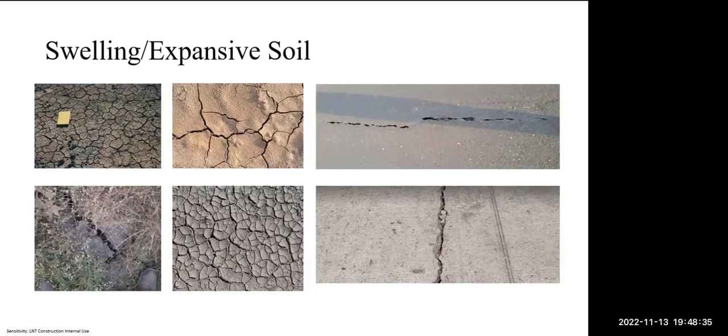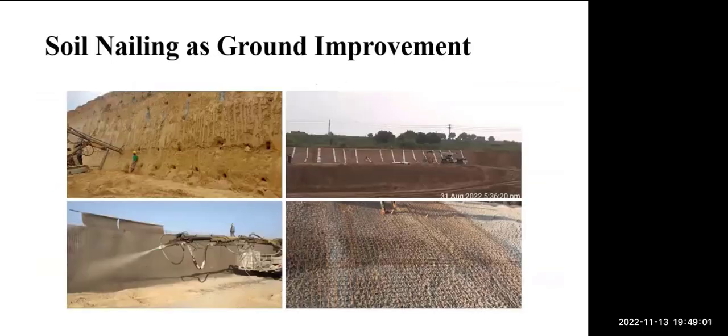A very common approach is to replace the soil, but it is not always feasible or economically feasible to replace expansive soils, because of their swelling and shrinkage characteristics and other critical parameters. It's very difficult to decide how we will decide about the ground improvement measures.